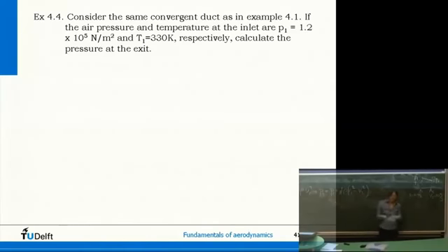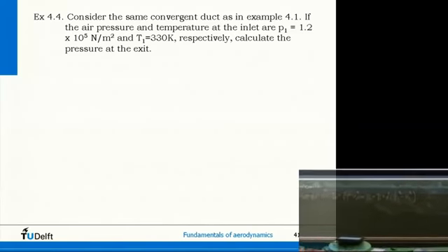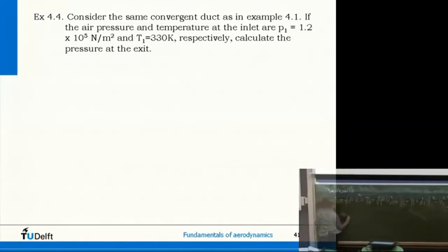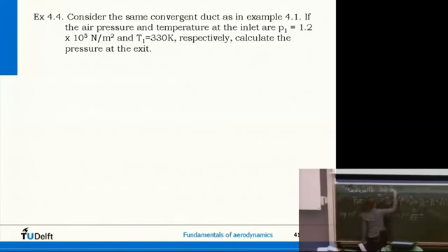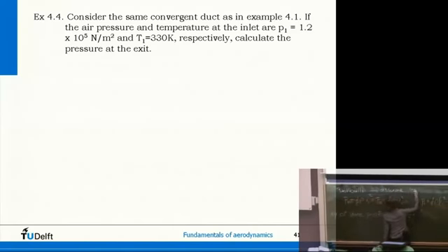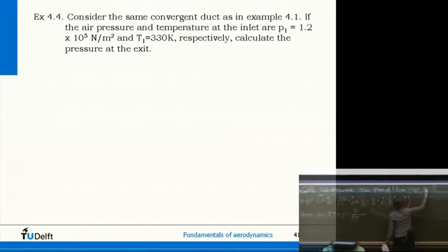We don't have the density yet. How do we compute the density? What is the relation we can use for the density? Rho is P over RT, equation of state. P is rho RT, so rho is P over RT. Now, we assume the density is constant, right, here Bernoulli. Low speed flow. Rho constant.